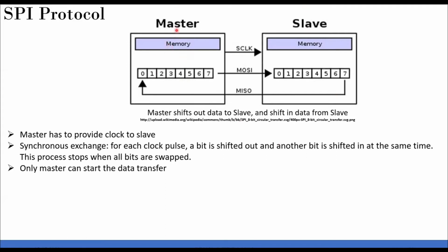So what happens is, from the memory, you load the data to your data register in the SPI. That will get transmitted to the data register in the slave with the clock. So each clock cycle, you get 1 bit of data transmitted. And at the same time, it is possible to transmit data from the slave to the master. Okay, so that is possible. So everything goes by clock. It's not like the UART where you have a start and stop bit to synchronize the transmission. But here there is a clock. There is no need of a start or stop bit in that case.